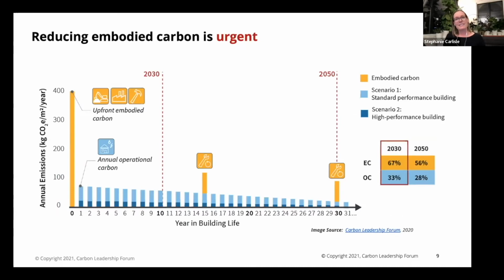And the very end of this intro, to wrap it up, is another key term that I like to throw out there and folks are really thinking about, and this comes back to the way we set goals and the way some of these tools are oriented, which is really harnessing the sense of urgency around embodied carbon. So you'll also hear people talk about the phrase upfront carbon. Upfront carbon or upfront emissions has to do with this huge burst, and what is often a very, very large percentage of a project's total life cycle carbon, which is going to happen all the way at the beginning. So this is the emissions associated with all those building materials and construction itself. On this graph, it's that big yellow bar over here.